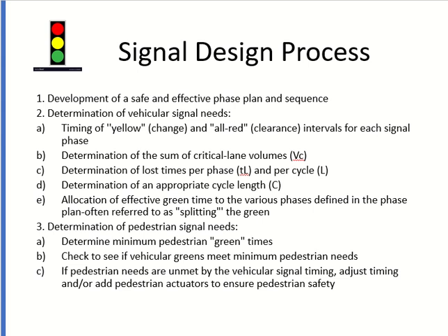First of all you try to find out how much time the pedestrian needs to cross. Then you compare between that time and the time you are providing him or her to cross. Which one should be higher? The provided time of the signal should be high. If it is not, then you have to adjust. Obviously you will adjust the signal time again, not the pedestrians. Ask them, run. Or you will die. So the last step is the pedestrian check.